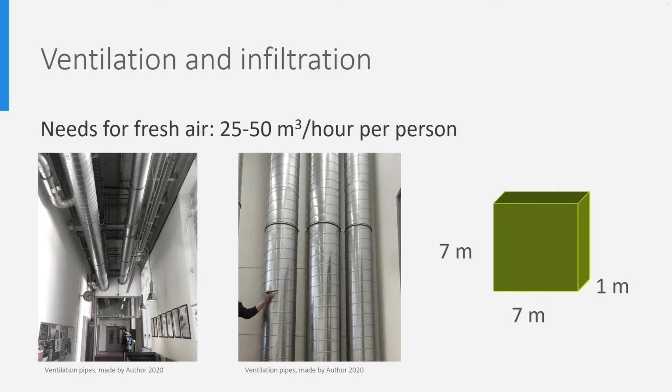Because it is tremendously important to have a healthy indoor climate, these ventilation airflows should not be reduced. Maybe in the future we will have well applicable ways of cleaning indoor air by which less fresh air could be used. Think of applications with UV light, for instance. But at the moment it really cannot replace fresh air. Unfortunately, because fresh air results in large heat gains or losses.